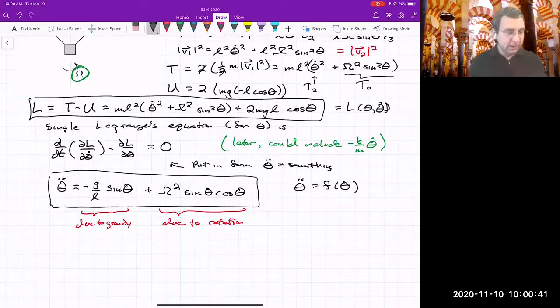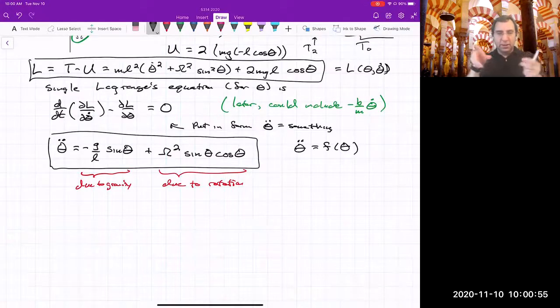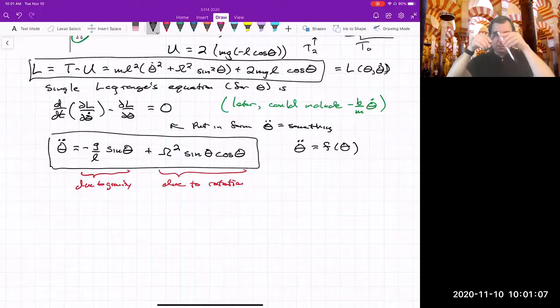Now what? We're going to analyze this in terms of a phase space approach. We want to find equilibrium points. So if you saw how the flyball governor works, there's actually some non-zero theta value where the two flyballs are; it's not equilibrium at 0. There's some equilibrium that's non-zero.